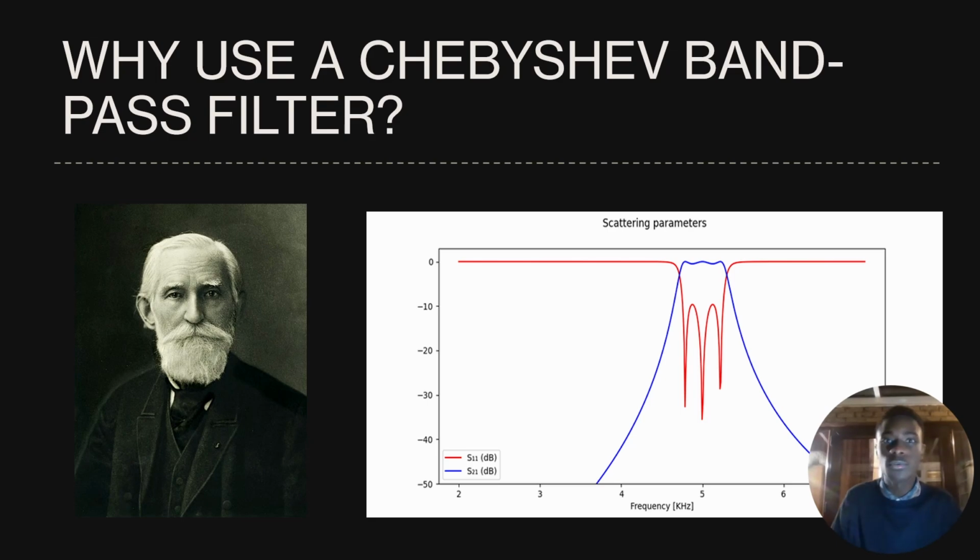Well, Chebyshev filters trade the small bandpass ripple for a much steeper roll-off compared to Butterworth filters of the same order. A 3-pole Chebyshev bandpass filter gives us that sharp attenuation outside the passband that we need and good frequency selectivity with only a small number of components. We use that controlled ripple to achieve sharper band edges, which makes it ideal for this bandpass application.